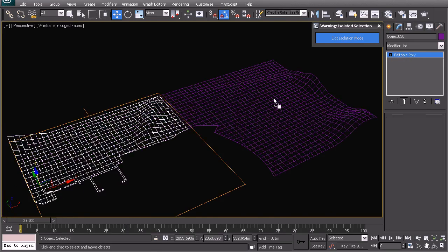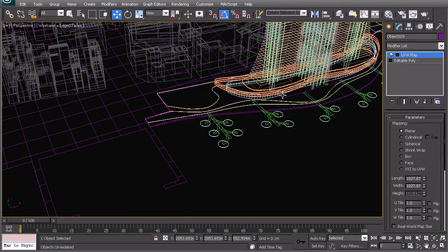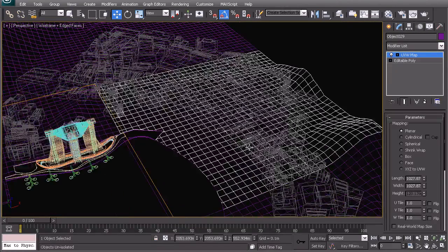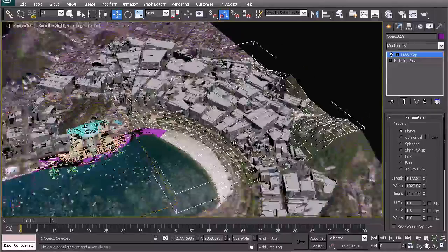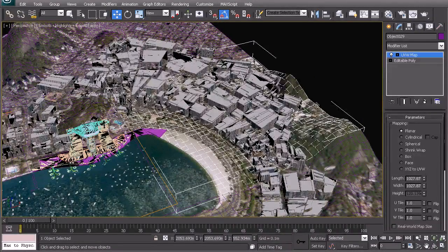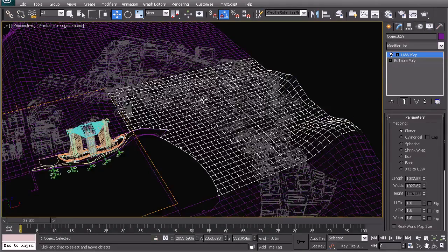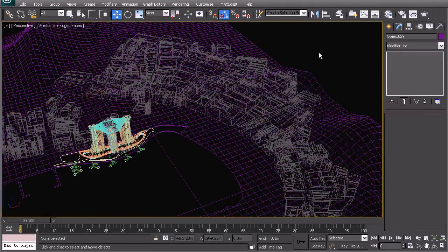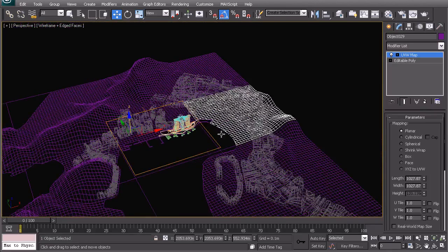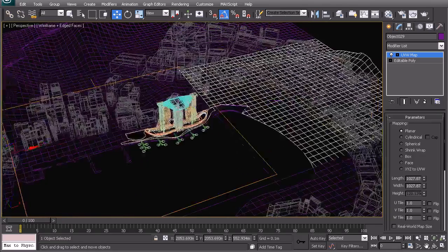So let's just see if we can do it this way. And if we're in luck, we wouldn't have damage to the UV map. So it looks like it's in the right place, but we should actually copy it beforehand, just before doing the boolean. So we must try not to forget about that, since now this one's UV map is actually on the side. But since they're all exactly the same size, it should be correct.